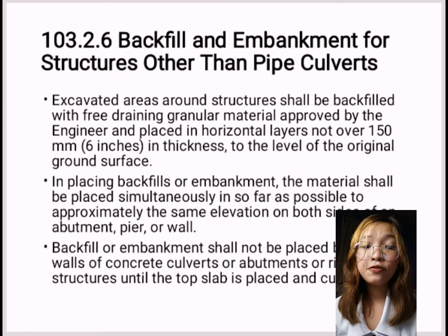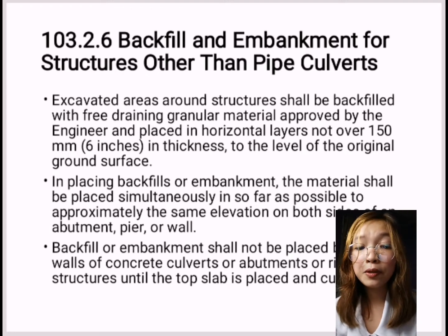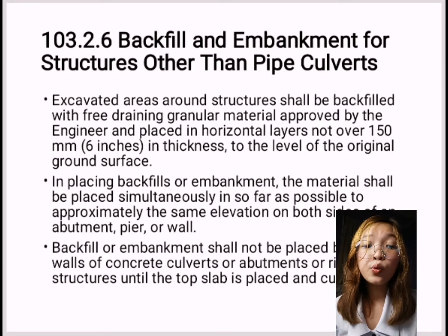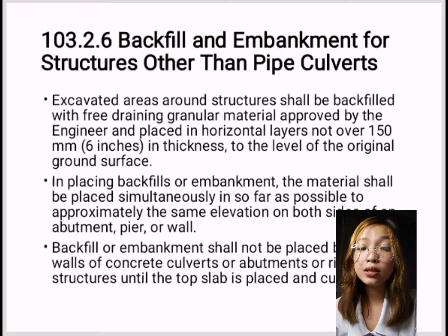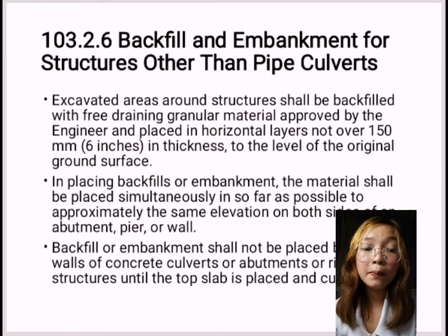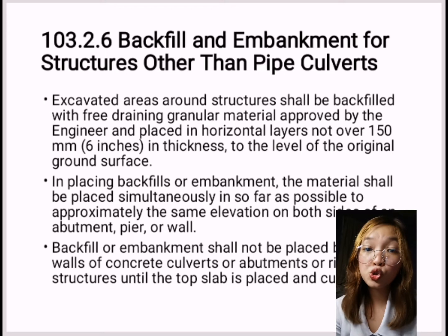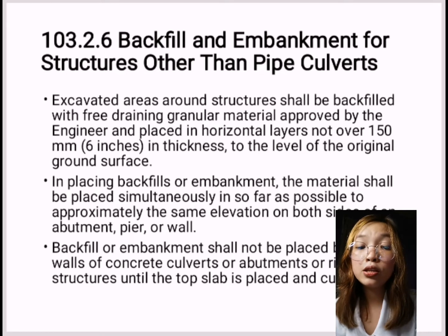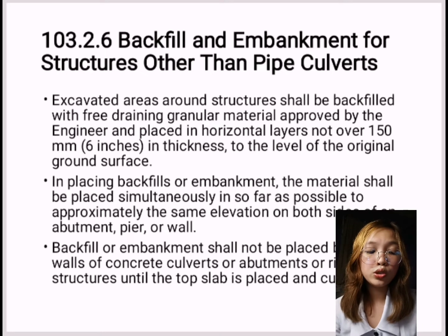And then backfill or embankment shall not be placed behind the walls of concrete culverts or abutments or rigid frame structures until the top slab is placed and cured. So backfill and embankment behind abutments shielded at the top of the superstructure and behind the side walls of culverts shall not be carried up simultaneously behind opposite abutments or side walls.